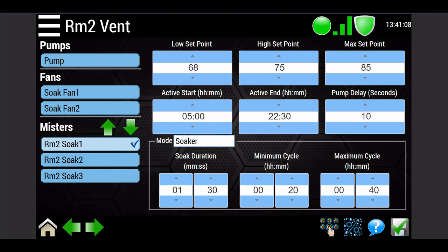So we're basically going to run through, we're going to add our water, and then we're going to have 35 minutes of the fans running, no extra water added. And then it'll take a look and, obviously decide if it will run another cycle or not. And if the temperature keeps increasing, we're going to get more water and less of just the fan running. So that is the soaker specific settings.